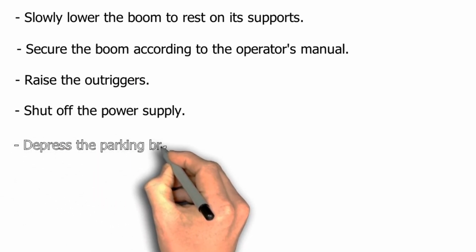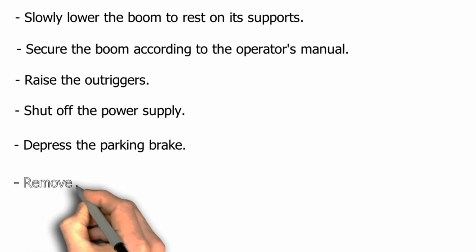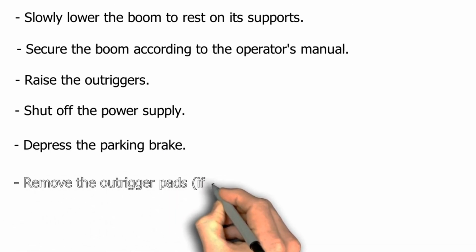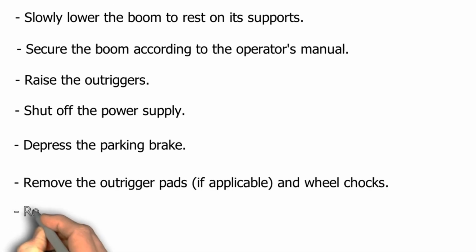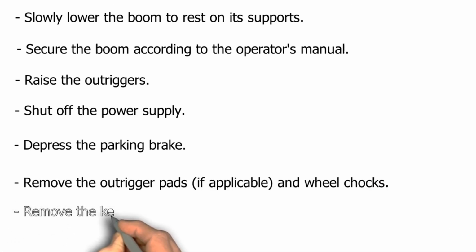Set the parking brake. Remove the outrigger pads, if applicable, and wheel chocks. Remove the key.